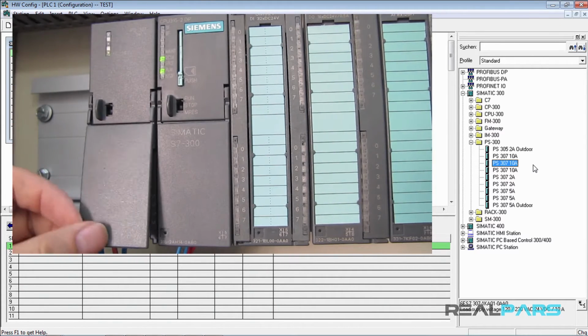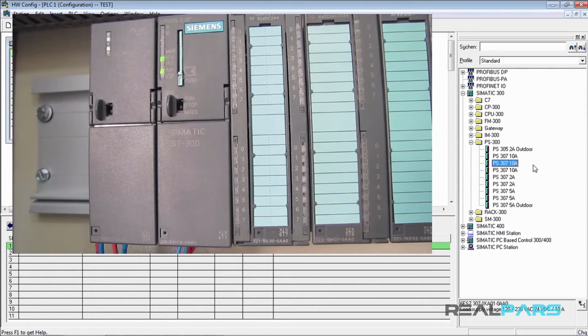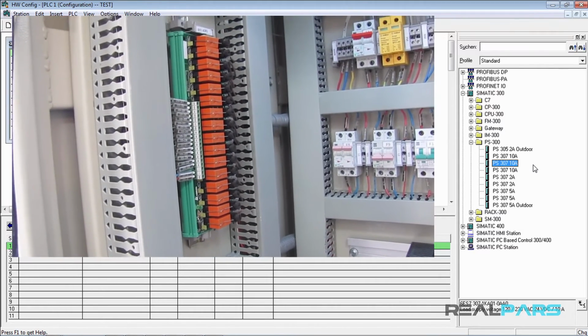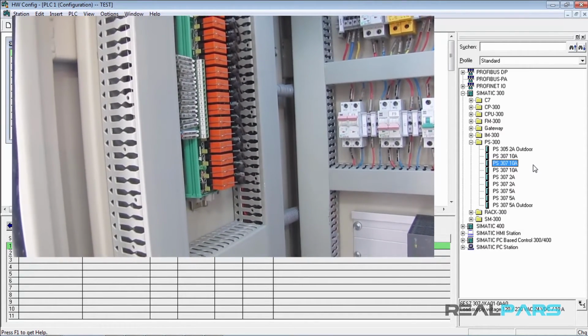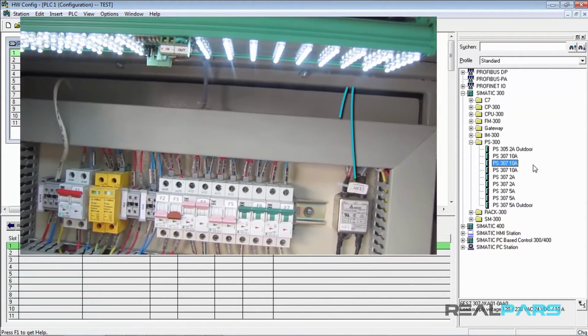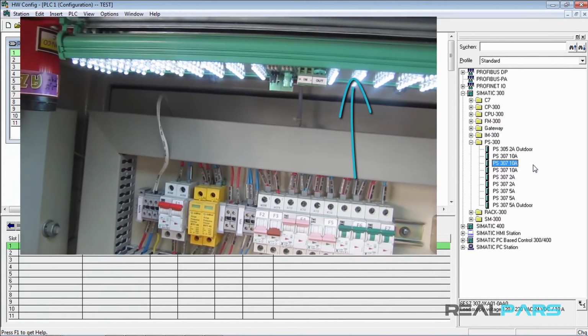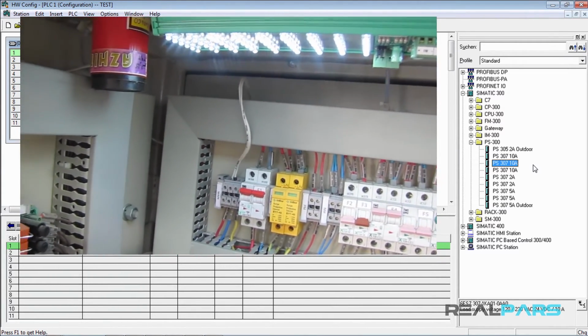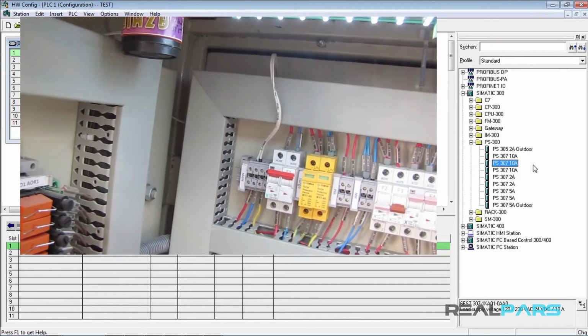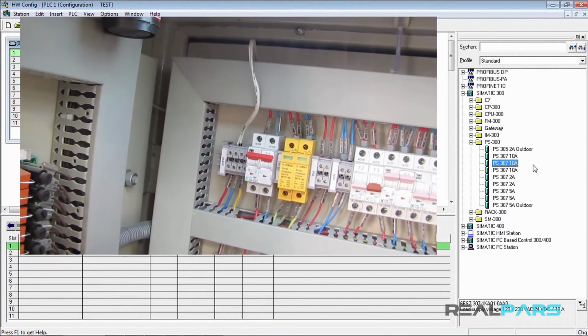Therefore, the output current that a power supply provides us should not be less than the total current that all the modules use up. In other words, the output current of the power supply has to be such that it is able to keep all the PLC modules on. In electrical enclosures, we have other facilities in addition to the PLC modules that also need a power supply to be on and that use current. For instance, if we use an LED light for the lighting of the inside of the enclosure, this light uses up a specific amount of current. Or, for example, if we have a signal beacon in the enclosure, this also needs a power supply and uses up electrical current when it's on.